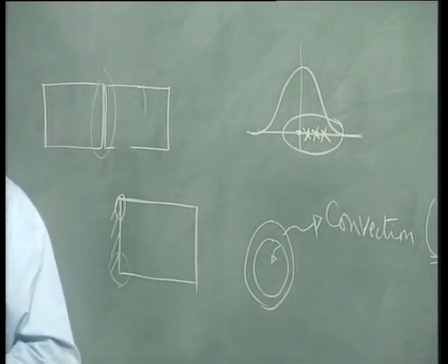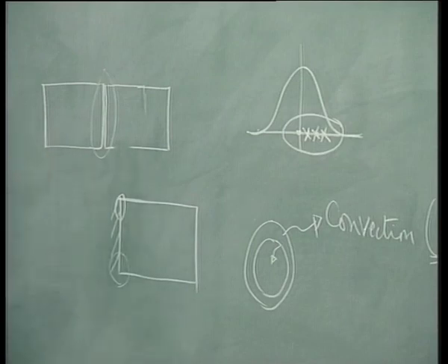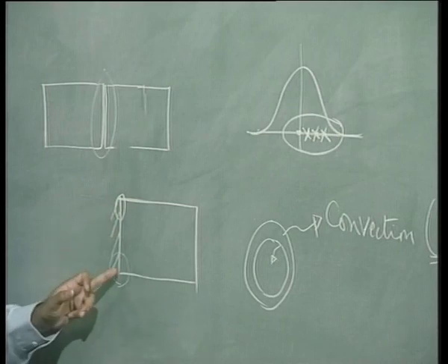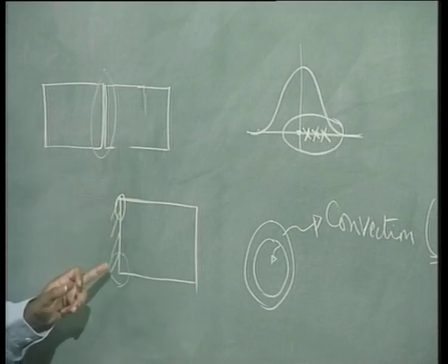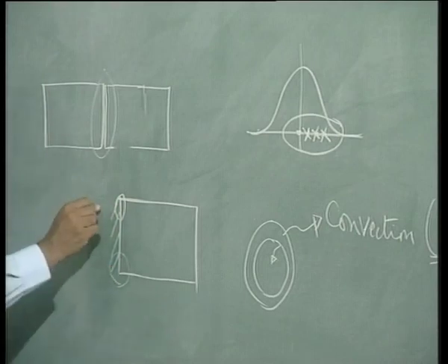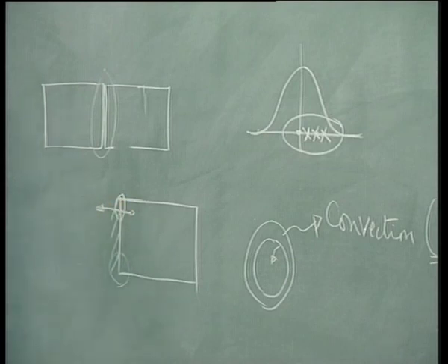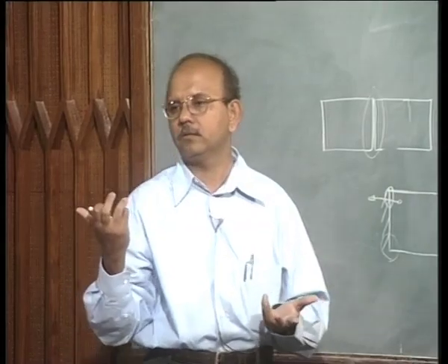What is the doubt I have raised? I said that there is a gap. Now, can you put a symmetry boundary condition here, that means that the displacements won't be there in this direction, and in this symmetry plane no rotation will be allowed.